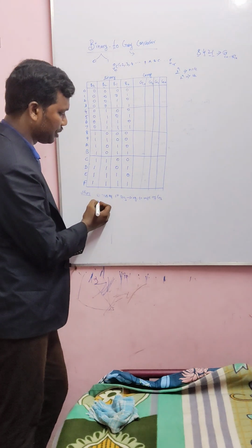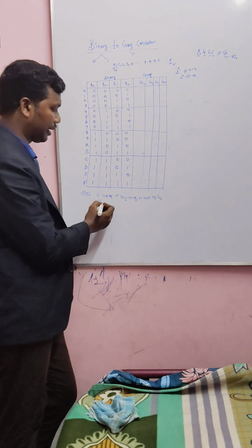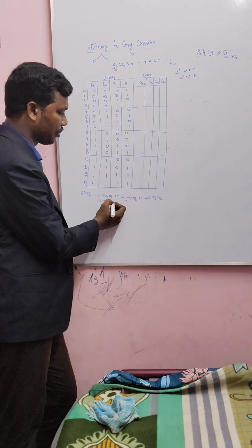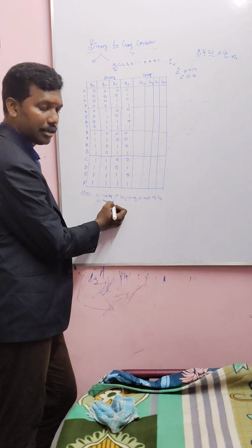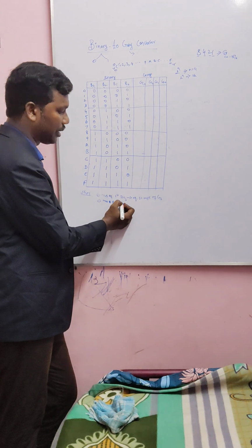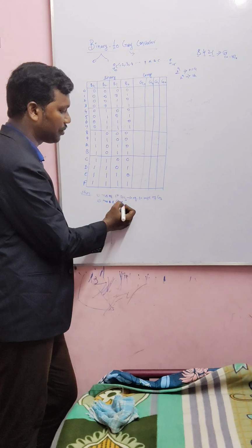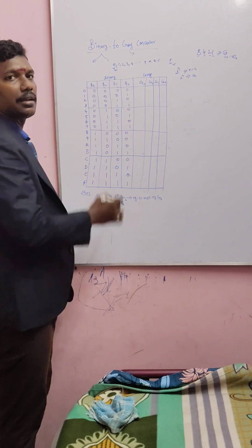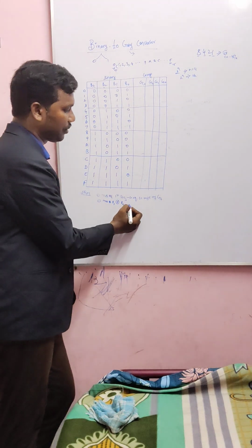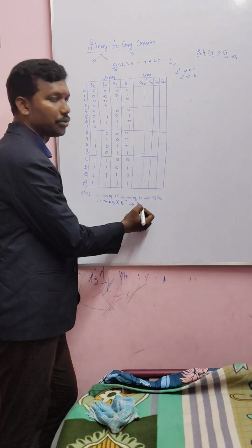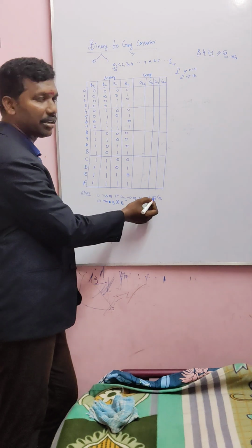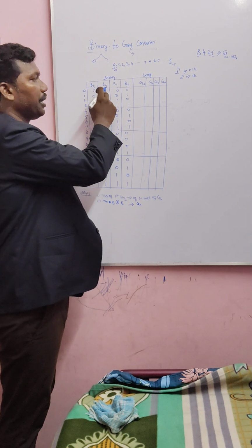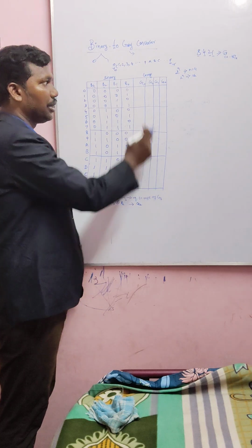Okay. Step number 2 is for the second bit. That means the MSB of binary, that is B3, XOR addition with the next immediate neighbor bit, that means B2. Do the XOR operation of B3 with the next immediate neighbor bit, so that is the bit of G2. Okay, hope you understand. First will be same as it is. Second will be the first MSB followed by the next neighbor bit in an XOR operation. That answer comes into G2.